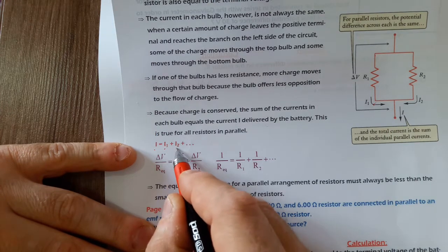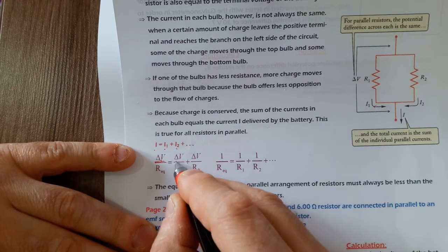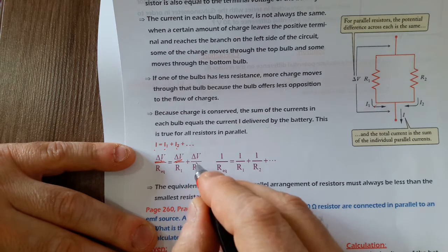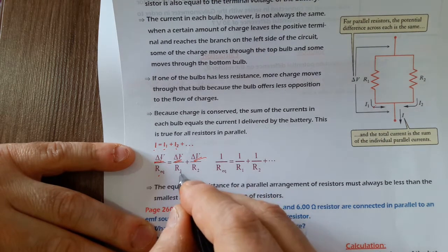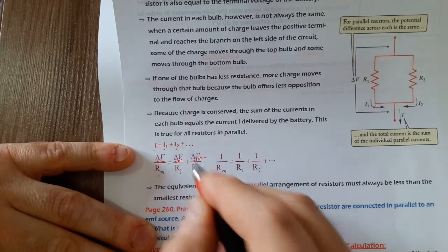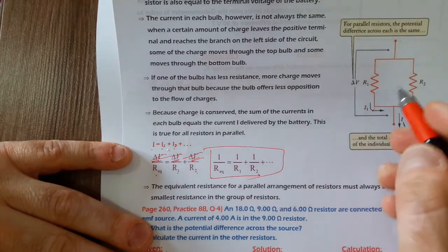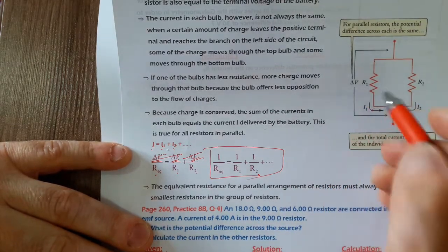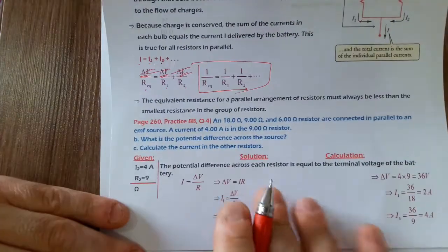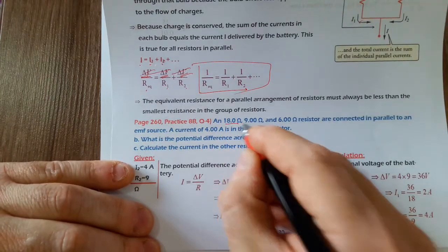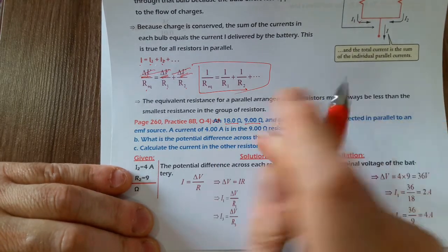So how can we calculate the equivalent resistance? Very easy. We are going to use these two things. One of them is that the total current of the circuit is equal to the current on the first resistor plus the current on the second resistor. And we know that the potential difference of the battery is equal to the potential difference across resistor 1 and across resistor 2. So delta V over R equivalent is I, delta V over R1 is I1, delta V over R2 is I2. This delta V simplifies, and you get the equation for calculating the equivalent resistance of resistors connected in parallel: 1 over R1 plus 1 over R2 is equal to 1 over R equivalent.